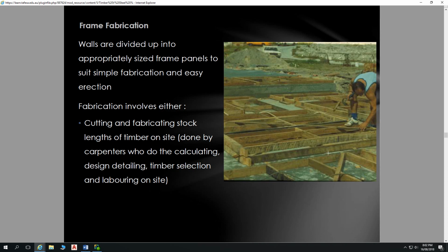Well, okay. Another thing that's changed: he's got a hammer. Yes, okay. Carpenters still have hammers somewhere in their kit, but they're probably pretty dusty. It's nail guns and battery gear, and that's made framing so much easier. If you can hold something in place, nail gun, that's so much easier. Anyhow, the actual design has not changed significantly, and that approach of building the frames on the slab and then tilting them up has not changed.